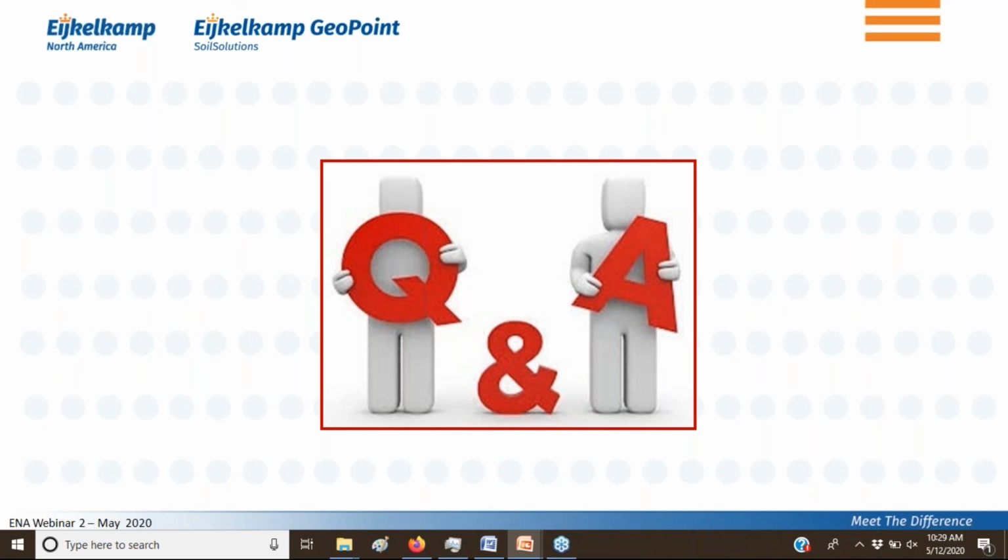If you have a large boulder in there, you will not be able to push your cone through. If you're in a landfill and you have some piece of concrete there, you cannot push your cone through. But softer, weathered rock, you might still be able to push your cone through. But generally speaking, more importantly, if you're going to get a split spoon down, you can get your cone down.